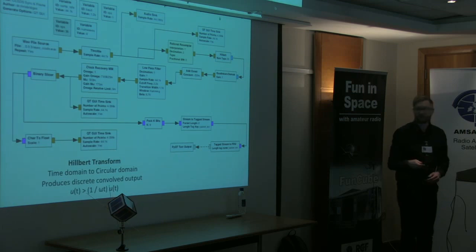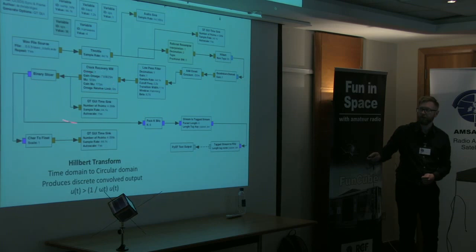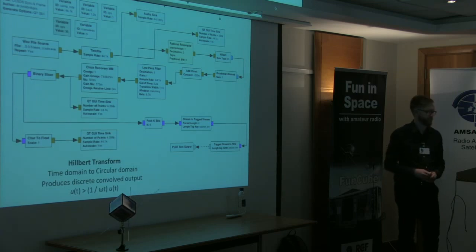But to do that gives you a complex output, and then just remember to convert it back into something that you can then use as a float, pass through some filters, recover your clock, binary slice it, pack it up, and then kick it out again through something else. You can start to see that you're just connecting these blocks up.